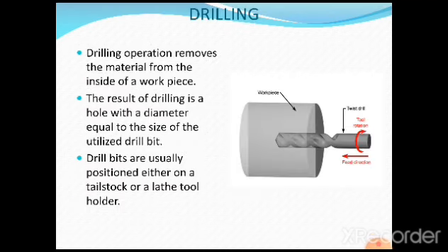So now let us understand the drilling operation. Drilling is a different operation, because as you know very well, drilling is an operation of producing a hole, a simple definition of drilling. Whenever we want to carry out the drilling operation on a lathe machine, it is necessary to hold the twist drills directly in the tailstock spindle, and it is pressed against the rotating workpiece, which is held in a headstock chuck.